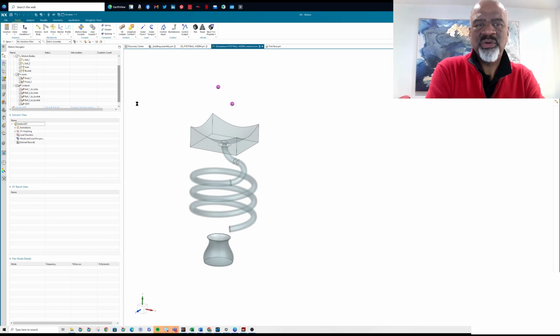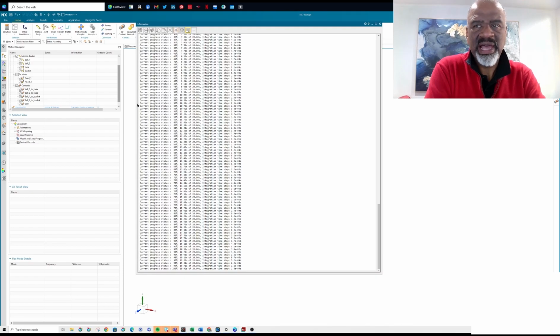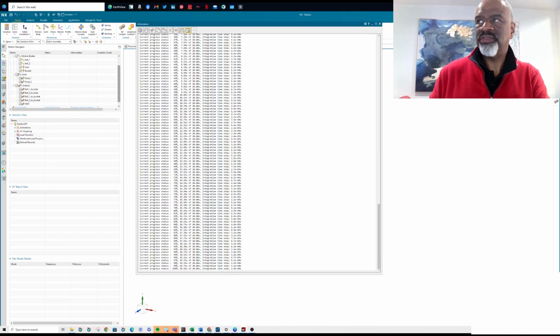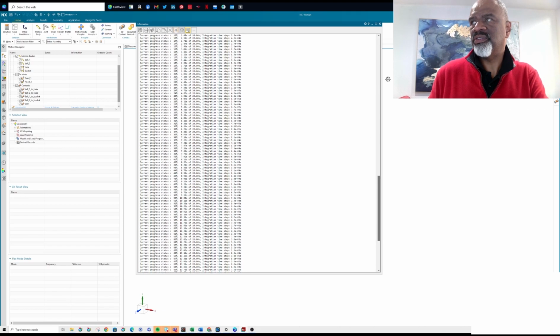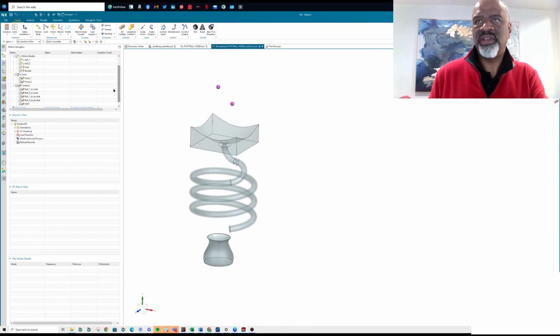But you can also assert mass property. If you have some rigid body that, let's say, is some representation that you get from McMaster-Carr or someplace like that, where the outside is modeled but nothing else, then you might want to assert the different mass properties. So here's all the steps, and as you can see, there's no warnings or anything.